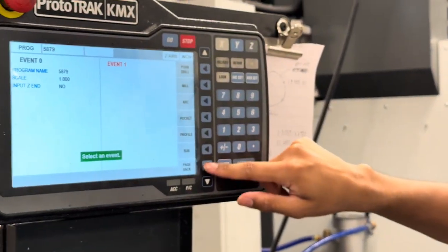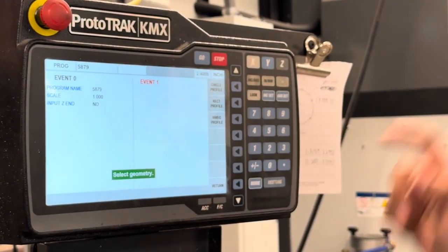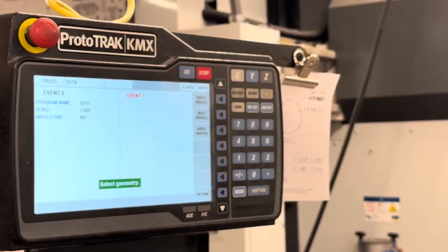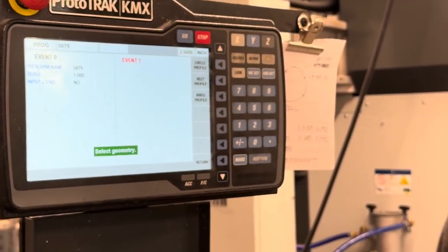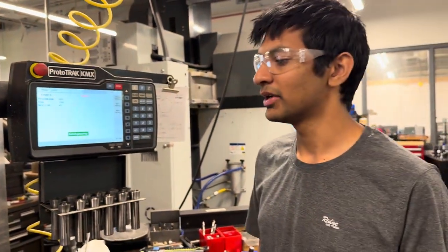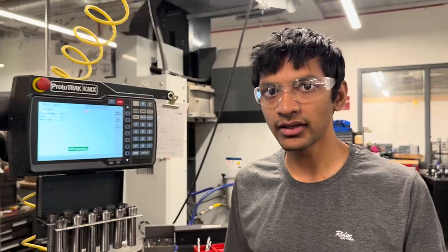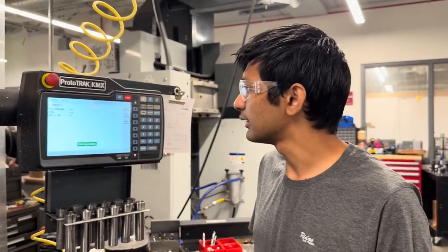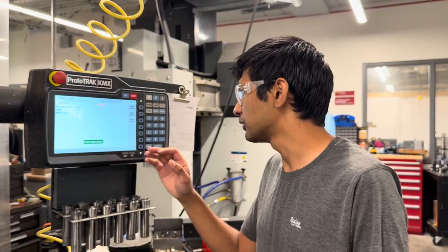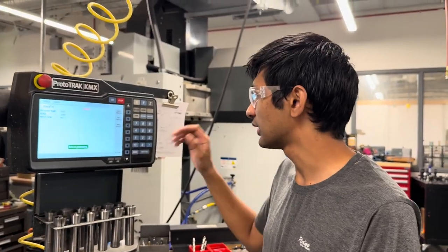Same thing with rectangular profile, it'll only cut the outside edge. So let's just say the water jet is being taken up right now, and you need a part to be water jetted, and you have the 2D contour. You'd profile the part instead of doing that.